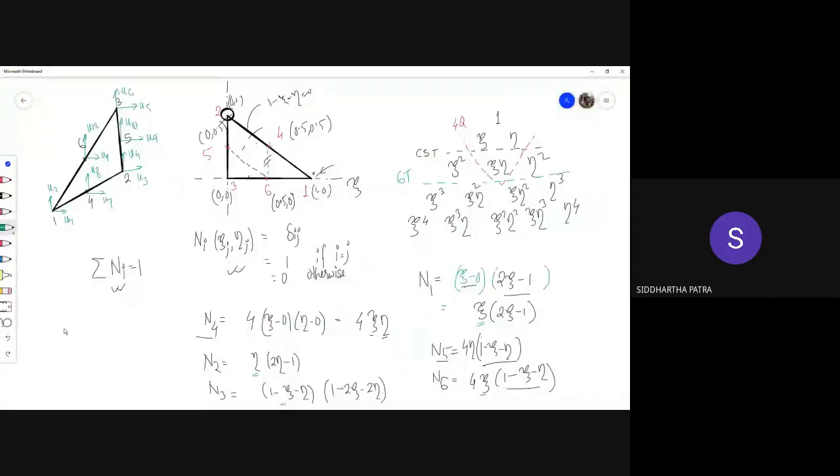So now you can imagine what the following steps are. You represent u as N times u hat. Then you again write N and e in N bar format, and take the gradient with respect to the natural coordinates. Then you get the Jacobian. From the Jacobian and this gradient, you get the gradient of the shape functions with respect to the physical coordinates, and eventually construct the B matrix, and that B matrix relates to your strain through this relation.